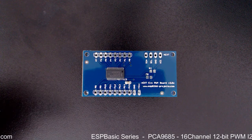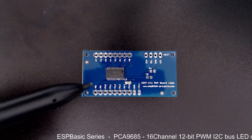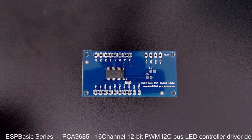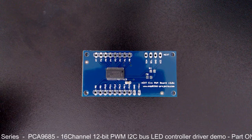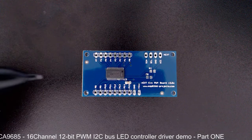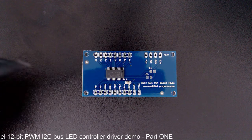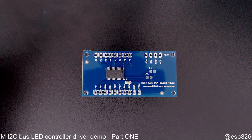You would like to go as high as possible, especially if you design a light fixture to use, for example, in combination with a camera. I'm just saying this because I finished about 2 weeks ago a design for a pick and place video camera, and if your PWM frequency for your light control is lower than 1 megahertz, it's just driving the camera crazy.